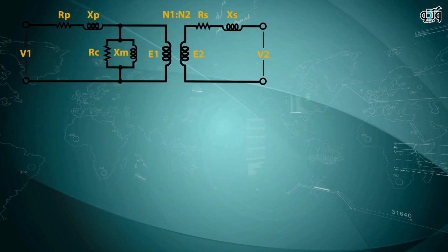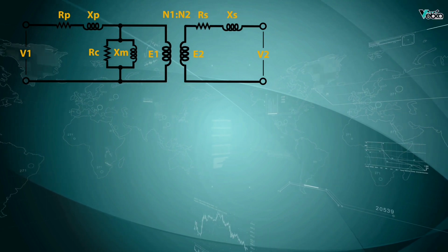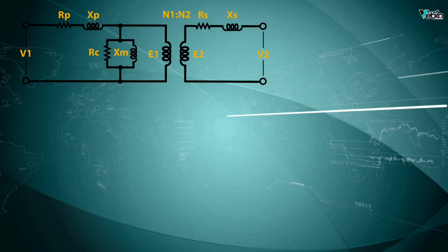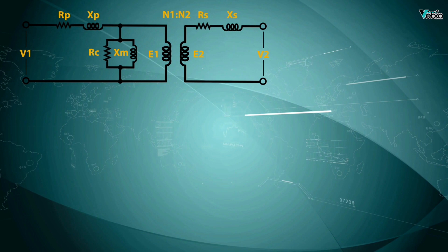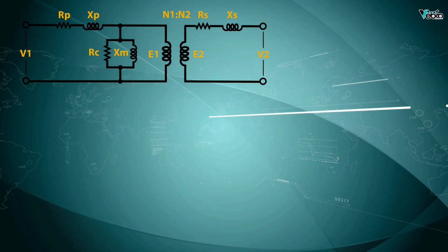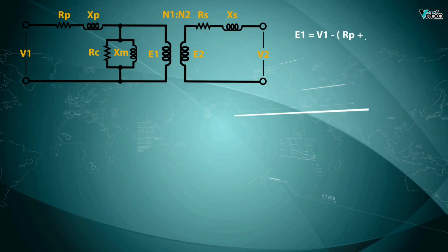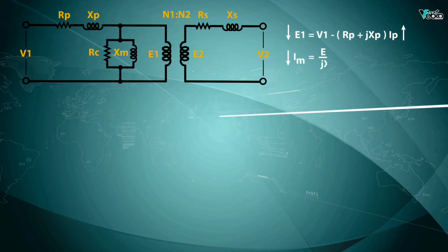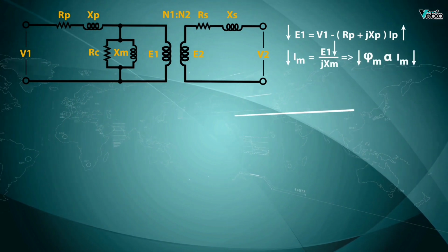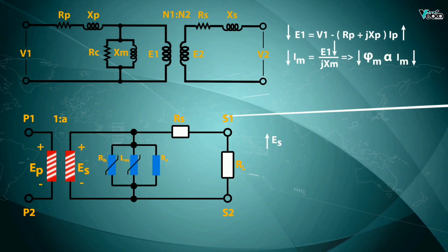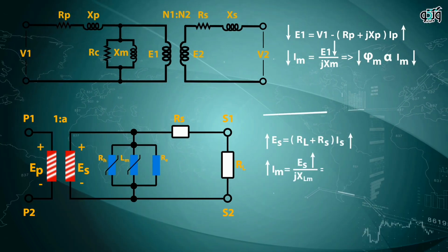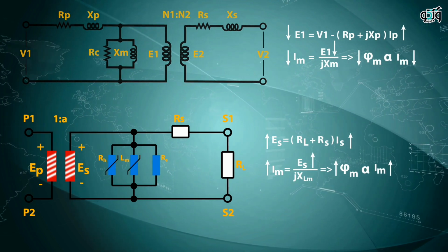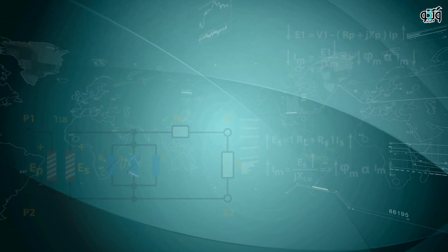CT saturation curve. As mentioned before, the power transformer recedes from saturation by increasing the current, whereas CT gets closer to the saturation area. The reason for this is related to the voltage of parallel branch, where in the power transformer, by increasing the current, voltage of the parallel branch decreases. But in CT, by increasing the current, the voltage of parallel branch in the secondary side increases and the CT saturates. CT saturation in a power system is caused by increase in the primary current because of occurrence of a fault which disables the CT to move the fault current to the secondary with correct ratio.